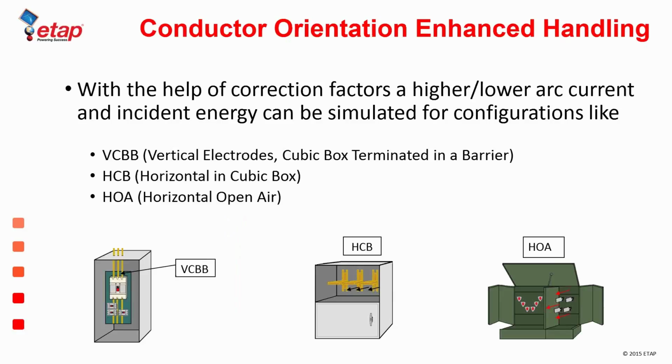higher and lower arc current and incident energies can be simulated within ETAP. And I say simulated because the factors are entered by the user, not by ETAP, and I'll go over how to enter the factors. So over on the left-hand side here, you have an illustration of a vertical electrodes in a cubic box terminated in a barrier. ETAP will provide you with a set of limits that you could use to simulate